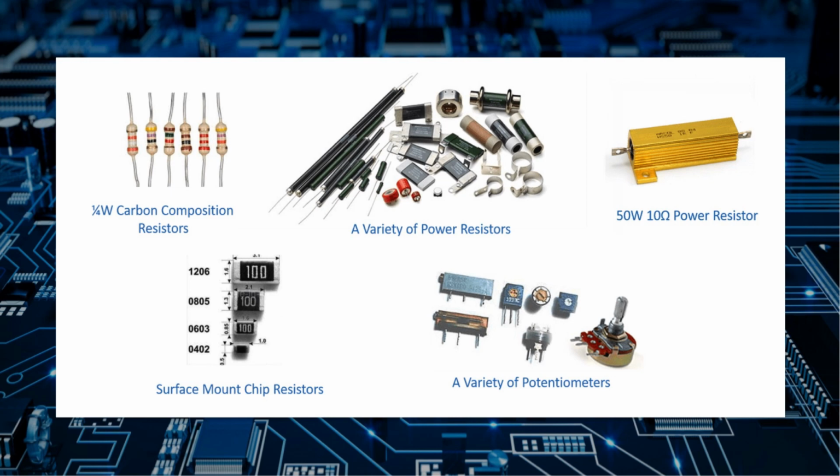All resistors dissipate power in the form of heat. The power the resistor dissipates during operation is a product of the voltage and current to which the resistor is subjected. Resistors are power rated in watts. And, as form follows function, power rating normally follows intended application. The almost infinite applications in which resistors are used means they're available in a great number of power ratings, from less than 1/8 of a watt to more than hundreds of watts.